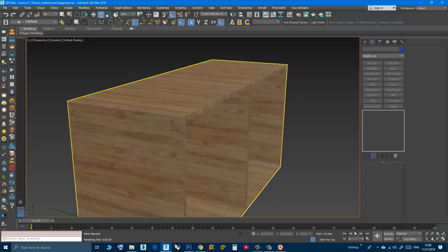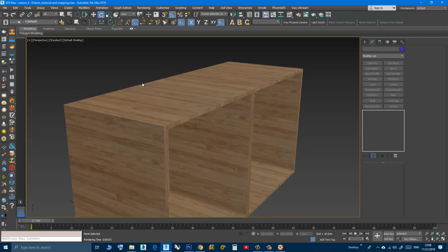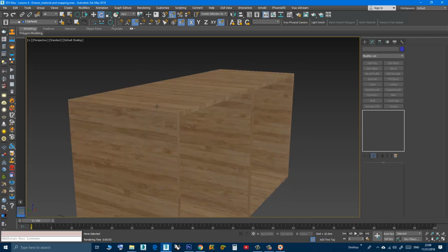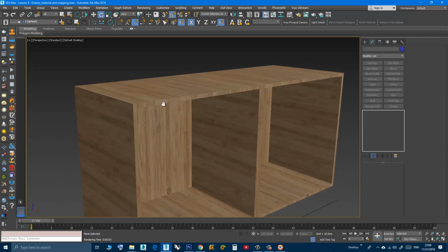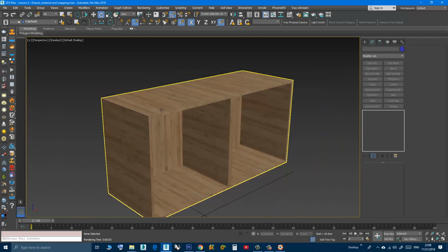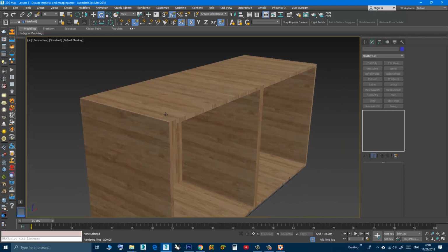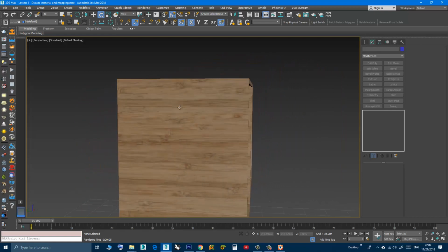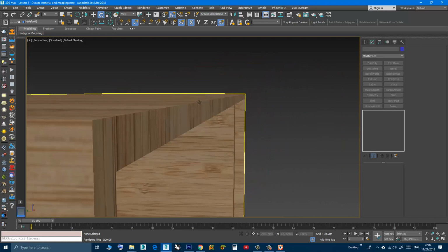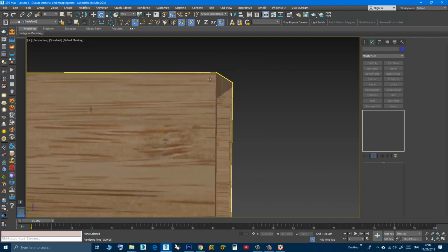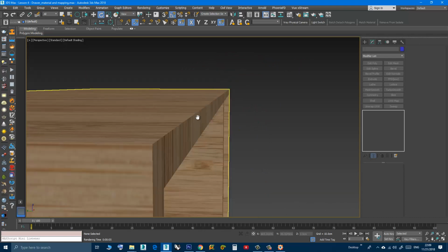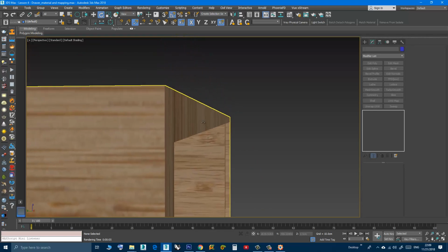You cannot push this geometry in the rendering like 1 meter up or something. It is limited, and also it depends on the point of view. You need to look at the object at a certain angle and avoid this parallel type of view. Let's say here, if I'm looking in this parallel way, the bumpiness will look ugly. It will not actually look bumpy at all.